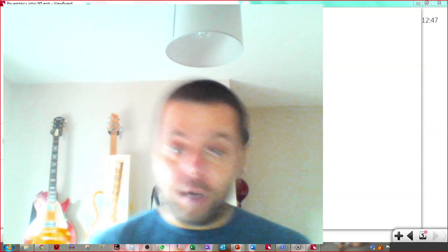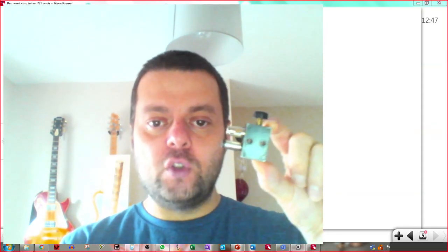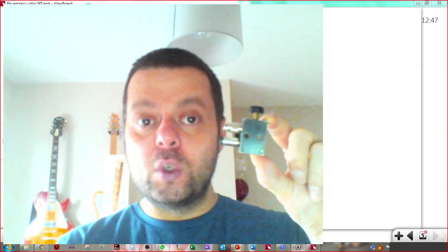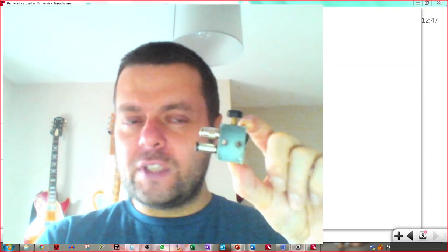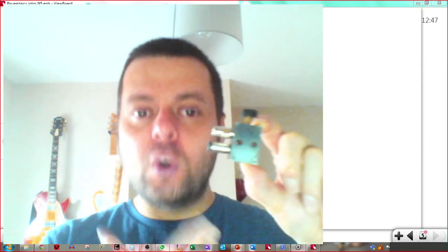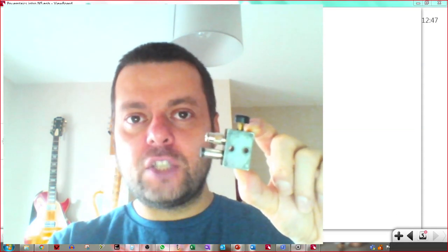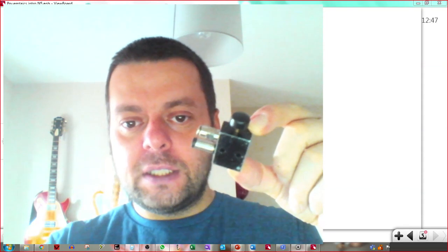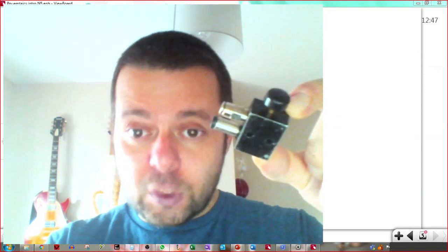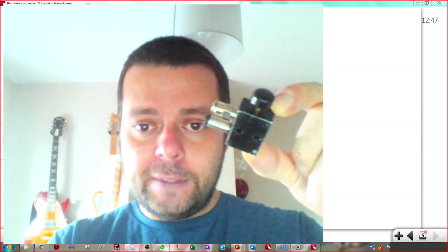Here's a 3-2 valve. So that's what a 3-2 valve looks like. Remember, it's called a 3-2 valve because it's got 3 ports and 2 states, but you can only see 2 ports on it. And I did reference that in the video, the idea that the third port, the exhaust port, just exhausts back to the air, so you don't actually have a connection for a hose on there. The exhaust ports are those wee holes in the top of the body. I can see them on the screen there, so you should be able to see. There's 2 wee holes. There's one at my index finger, and there's one at the other side.